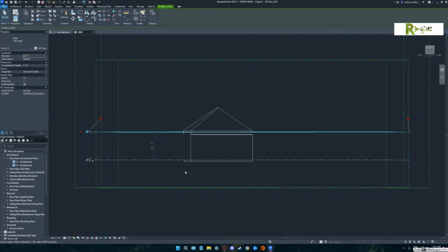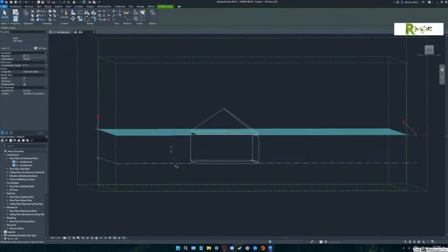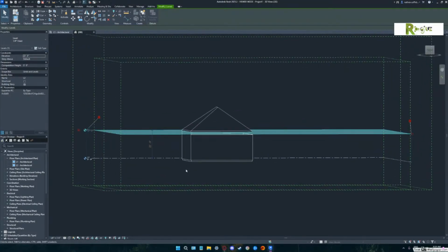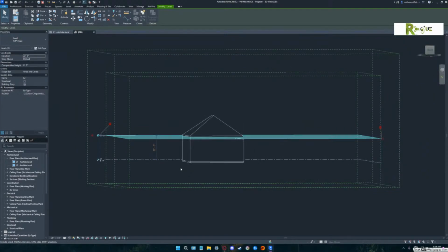What we draw first, and I think you said you wanted to do a sports arena as your project. For a sports arena, for large scale buildings, we get into the real order that Revit wants you to draw, which is the first thing that you draw is your levels. You figure out how many levels you're going to have approximately.